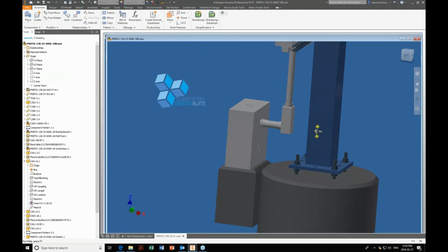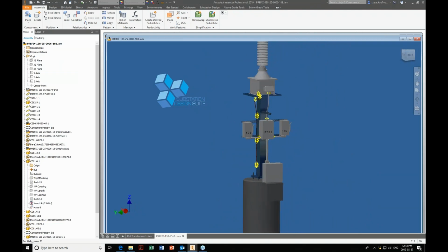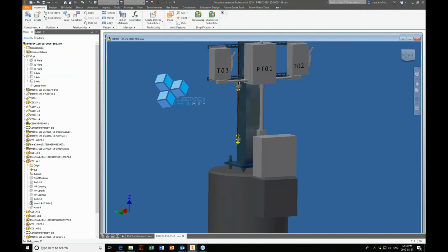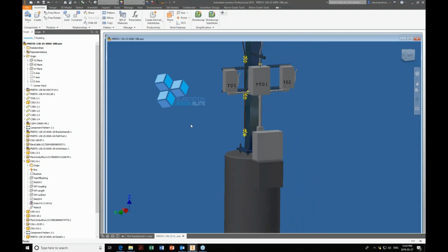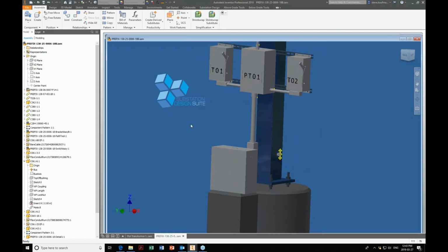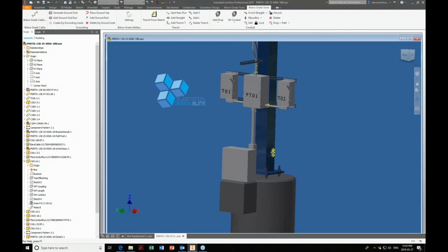Typically with the islands, you can see I put as much information as I can in an island. I don't continue my grounds down below my last joint. That's where I ended, and you'll see when we do a little drawing of this. You can see we have conduit in here already. I'm going to come to my below grade tools. I'm going to delete this piece of conduit. I'm going to delete this one. And remember, this deletes it out of the file path too.